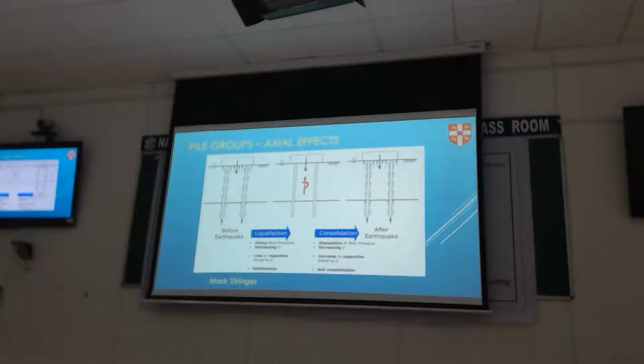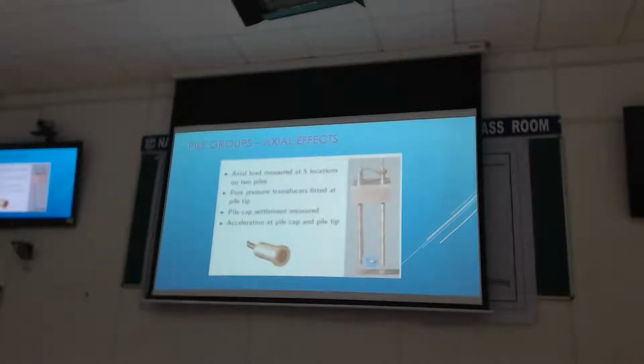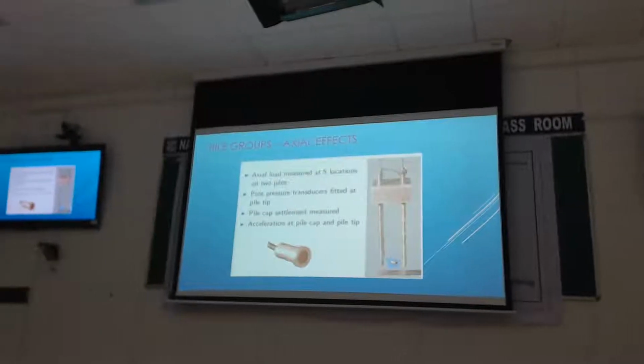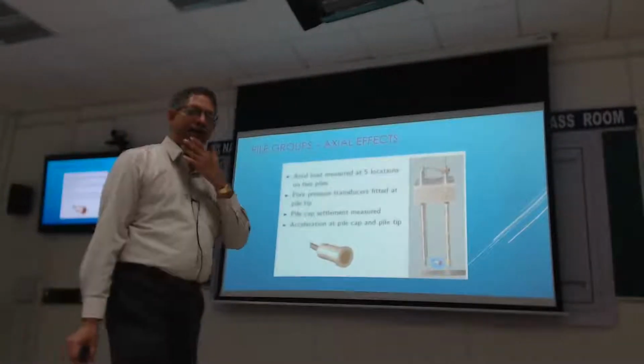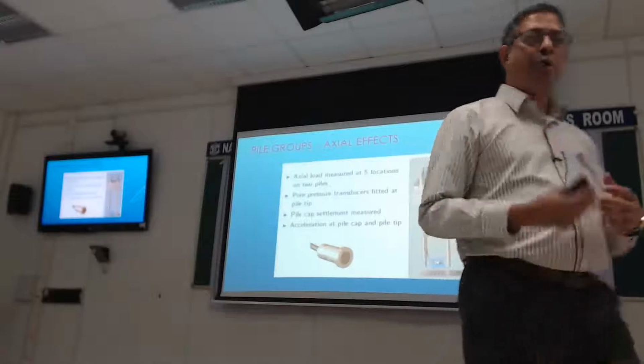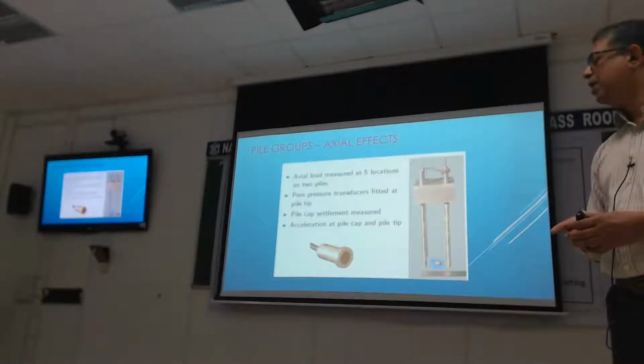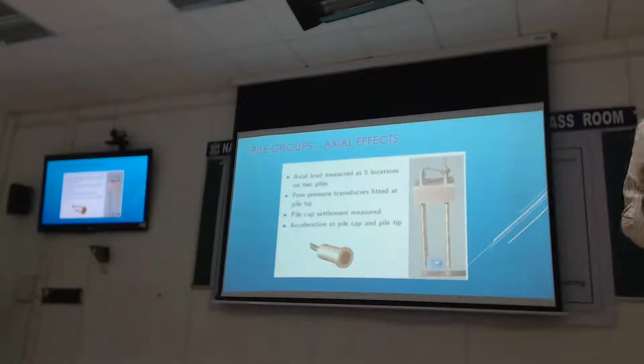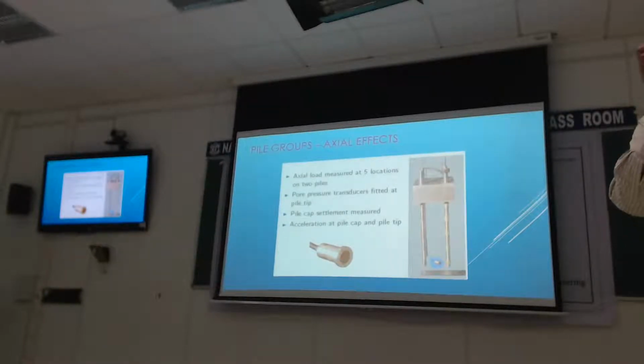So we set about trying to understand what happens in between. I'll tell you part of the story now and part after lunch. To study this problem, we had to do some unusual things. Normally when you're doing these tests, you gauge your piles to measure bending. Whereas for this, we had to gauge them to measure axial load, because we want to know what's happening to the shaft capacity during the earthquake loading.